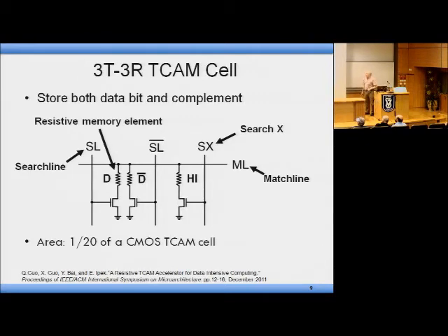I do a lot of research with him, and so he's offered this new TCAM structure, which is kind of neat. It's meant for search. So you have a large signature, a wide variety of number of bits, and by accessing the search line through these Memristor devices, you can put a big signature across a line, do a very, very fast search and see whether you've accessed that state. D and D bar define whether you have or have not, and X is the don't care state.